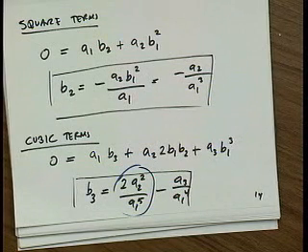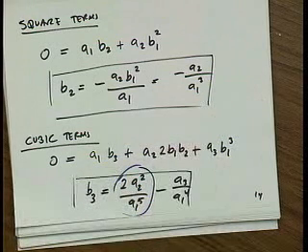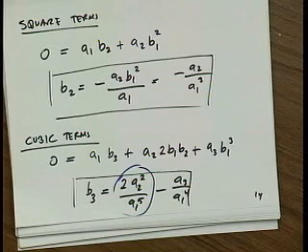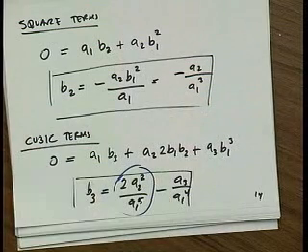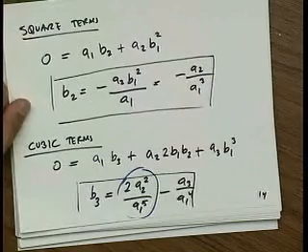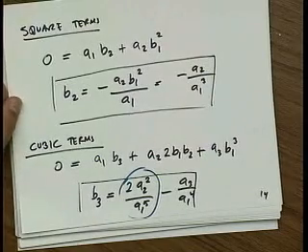Okay? So in particular, if you think of a square law device, if you apply an input voltage, the output current doesn't have any cubic, right? But what if you apply a current to the drain and look at the input voltage? Well, certainly that's the reverse. Certainly you can solve that analytically. You don't need to use this technique. But if the equations were more complicated, you would, and you would find that actually there is a cubic term. All right. Any questions about that?